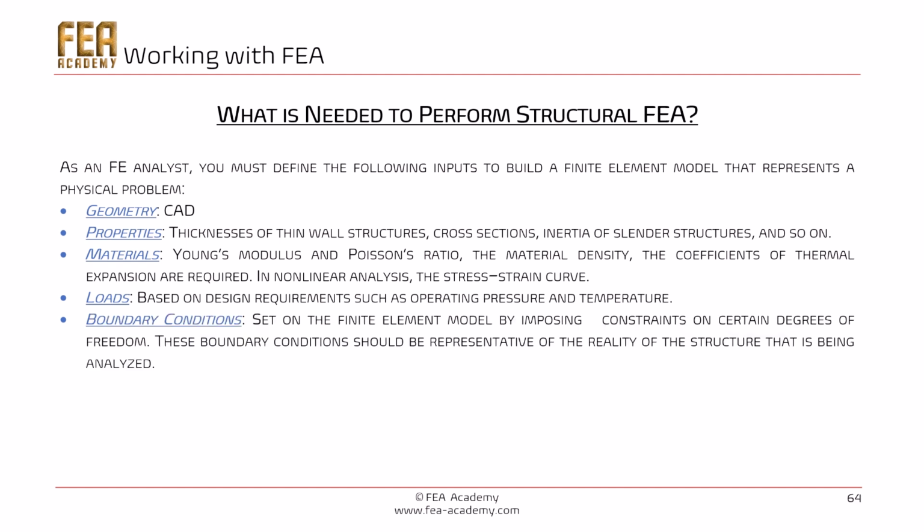Finally, we have the boundary condition. To solve equilibrium equations, all rigid body displacements must be removed. So to achieve this, the FEA analyst must specify appropriate boundary condition for the finite element analysis. Practically speaking, the boundary conditions are set on the finite element model by imposing constraints to certain degrees of freedom. These boundary conditions should be representative of the reality of the structure that is being analyzed.